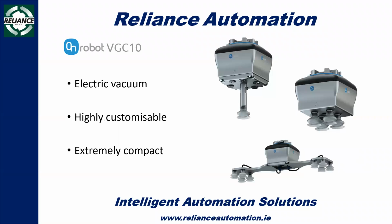During the video, we would have seen the VG10, which is the large vacuum gripper. Well, this one is the VGC10. This is the compact version of that, and the little brother of the other one. It's a very, very small piece. What's great about this is, although it's a vacuum system, the piece is controlled by electronics, and there's actually a motor and a vacuum system within the tool itself. So you don't have to have pneumatic lines running separate to the system.